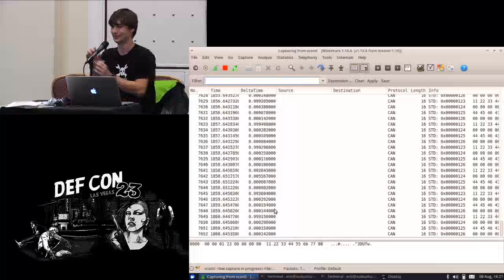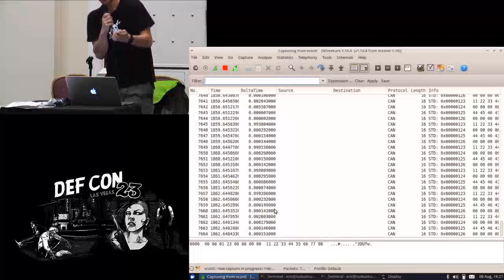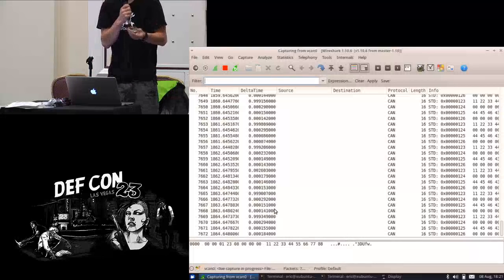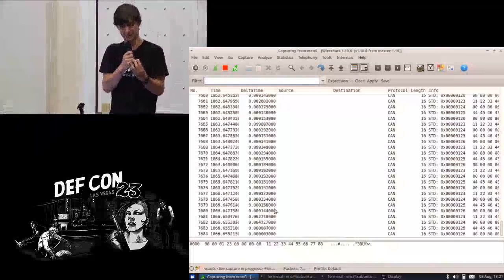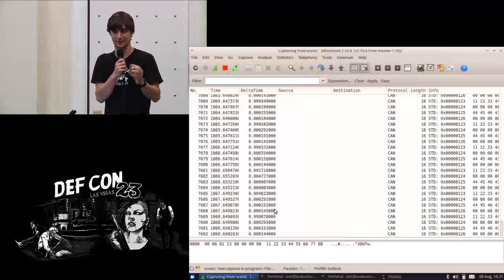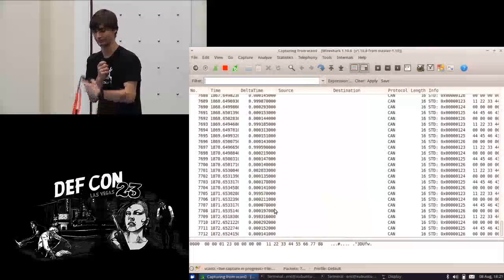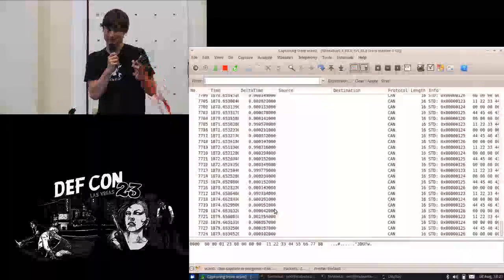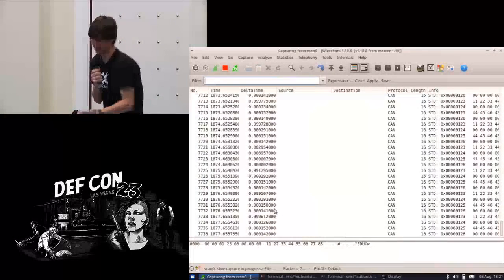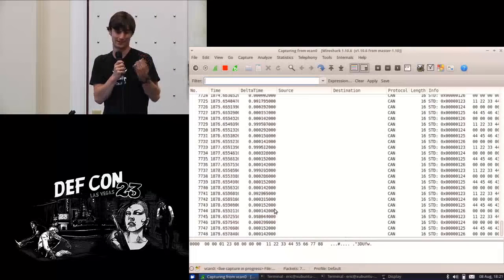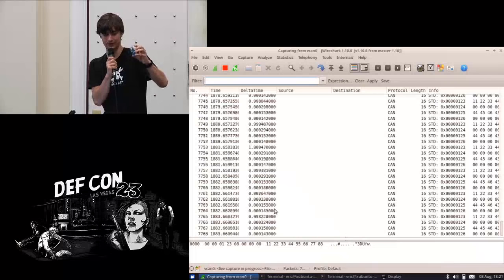Yeah, so it's this device that I built. Basically, I was like, hey, I should build an open source hardware thing. So I did. This is using the STM32F0, which is remarkably similar to the microcontroller on this guy. Slightly different package. The cool thing about it is it can do USB and CAN at the same time. So this is essentially a USB connector, microcontroller, CAN transceiver, and some jumpers.